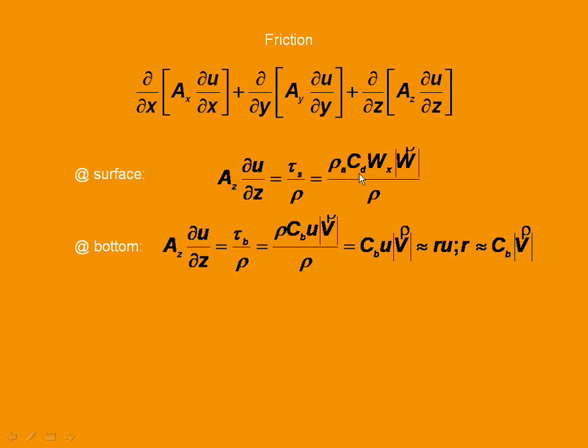Same order of magnitude, but should it be larger or smaller? Which is easier: for the wind to move the water, or for the current to move the bottom? For the wind to move the water, so the drag coefficient should be less for the air-water interface, right? But for the water-sediment interface, or water-bottom interface, how much larger approximately? 2.5. 2.5 times 10 to the minus 3 is the drag coefficient.